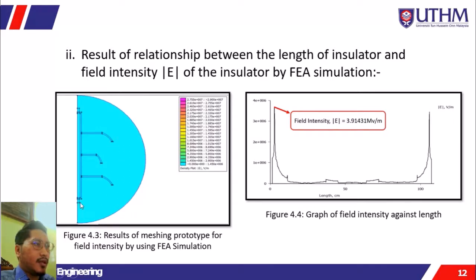We use this design because the highest diameter will protect the shortest diameter from wet conditions and maybe dust pollution, and the insulator can be used longer. Then the last shade is the highest because it is nearest to the pin and it can withstand the highest voltage there. That is the analysis we can get from this result.